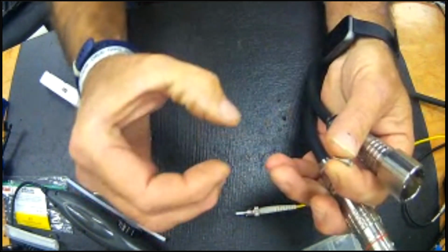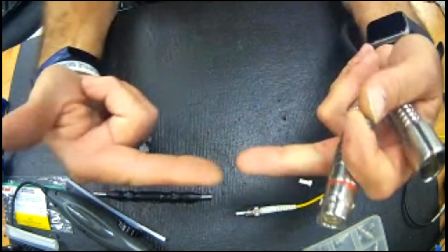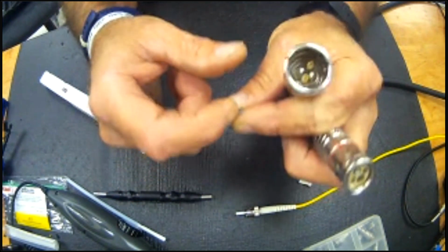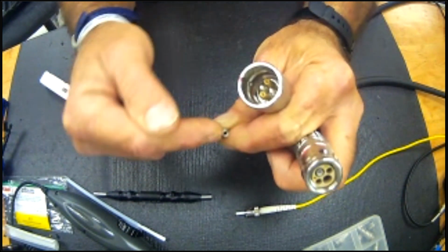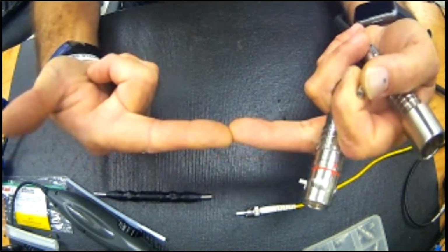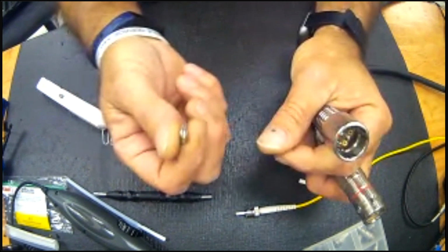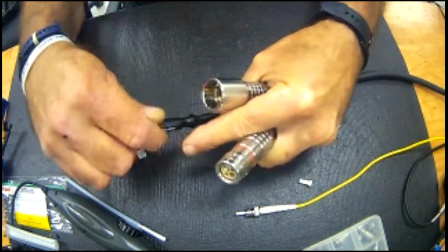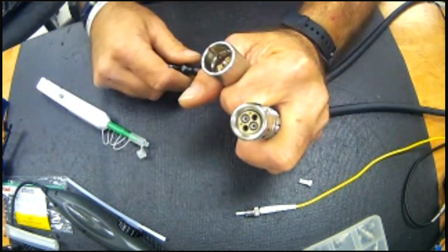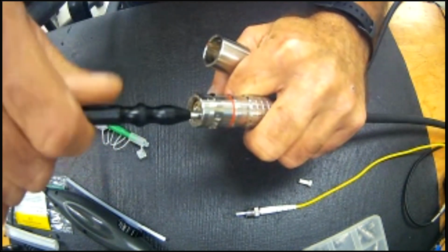Inside of an alignment sleeve, all alignment sleeves, is a C-shaped piece of zirconium. It basically flexes a little bit as it allows 2 contacts to align under pressure. Dirty contacts may cause this to break prematurely. A broken piece of zirconium inside of an alignment sleeve is good for 20 dB of attenuation. I kid you not, those 2 contacts won't even come close to aligning. They will be so offset, you will assume that your cable is broken, when in reality, it was a $10 alignment sleeve and a $30 tool that you needed to own to install and uninstall that alignment sleeve. So again, extracting the alignment sleeve: thread it on, pull.